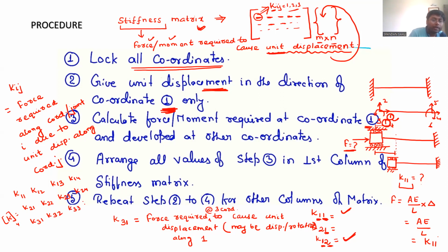Now you are able to correlate how things are getting added up from week 6 onwards. You told me in the force method the same concept, when we constructed the force matrix. When you write the equation, suppose the D matrix is due to the external load, F is the flexibility matrix, and X is the unknown.